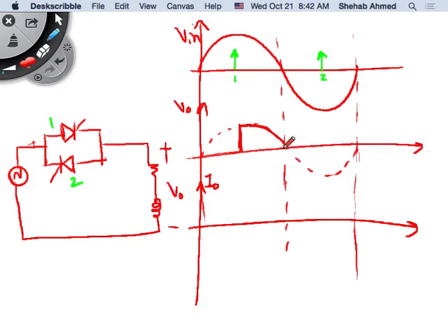Until here, it's like the resistive load case. And then what happens? It depends on how big your inductor. Exactly. Then we have to look at the current waveform, so we don't know where we will stop. So what will the current waveform do? Here I have an RL load. I have connected my source to my load. So what's going to happen?